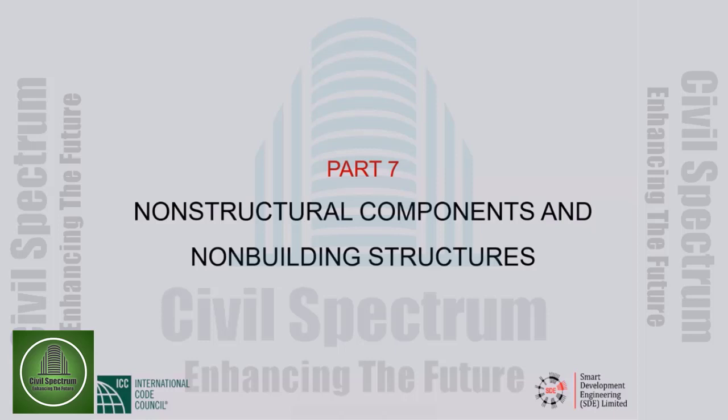What is different? Here the deflection limit is different, so my question arises. Deflection limits for roof members supporting plaster ceiling, roof members supporting non-plaster ceiling, and roof members not supporting ceiling. For floor members, the one number that is given is the same as for roof members supporting plaster ceiling.